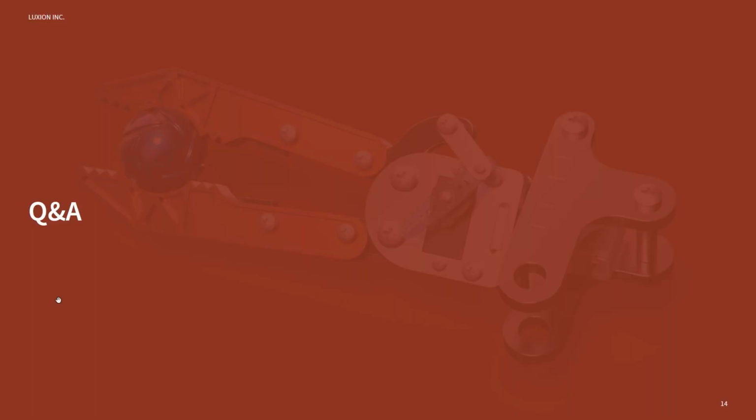If you don't select a component and you click the update button, then it's going to update the entire assembly, even if there weren't changes to other parts. So it's a little more efficient just to make the selection of components that you want to update. I hope that answers the question. I think it does. Yeah, I think that brings a lot of clarity to it.